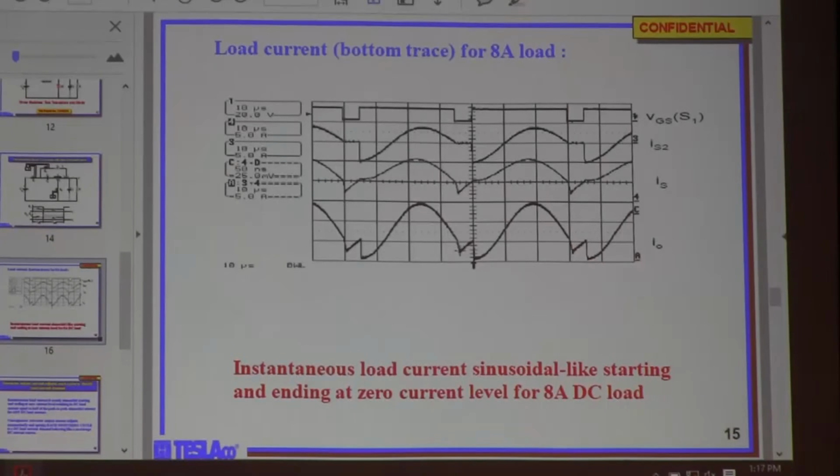Doesn't it look like a perfect sine wave with a little glitch here? You see, if you overcome this, wasn't that like a regular sine wave? When I saw that on a scope, I said, my God, I have a digital scope. What do I do? I just put it on a digital scope, save this waveform, and shift it by exactly half a period. And what do I get? I get a Tesla working again. Two sine waves shifted 90 degrees out of phase.